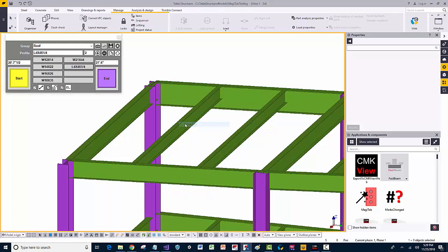And actually here's a good case of what I didn't expect, which is that I need to change this back. So I could put 2 angles in, or I need to change this back to 1 or 0, something less than the quantity of 2, and then that way it's prompting me to pick points. Before, when I had this at greater than 1, it's basically saying that, oh, you're trying to put more than 1 angle in, so you need to pick the parts to define that. So here we're just going to go ahead and say nearest, and we'll pick along there, and now we have an angle placed here in the model.